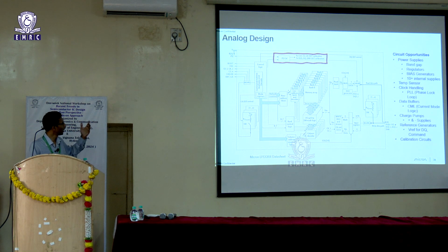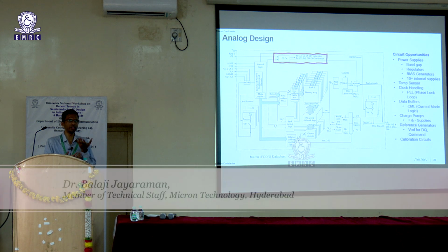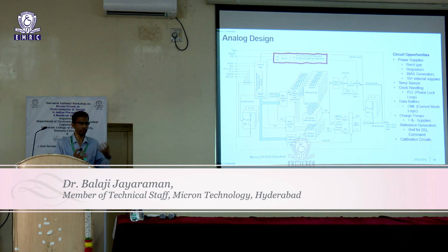And similarly, there is a lot of analog that goes into the system as well. We can start with a simple DRAM operation. It's a 1T 1C cell. And suppose we are operating at a VDD domain. Your gate voltage of this NMOS can't be VDD if you want to operate your cell at VDD. It has to be slightly above that, because you need to overcome the threshold voltage of the NMOS transistor. So you need to have a mechanism to boost the voltage from your VDD domain.